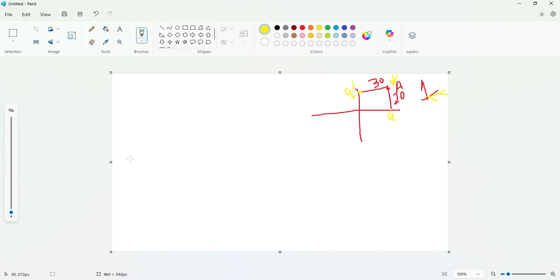And to plot this on the XY line, as I told in the previous slide, we have to plot this projection on the XY line. This XY line passes through the origin in 3D. So to put this here, we have to rotate this HP by 90 degrees in the clockwise direction.